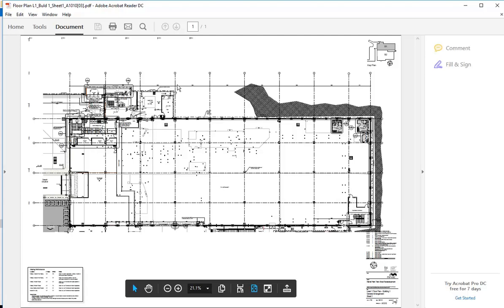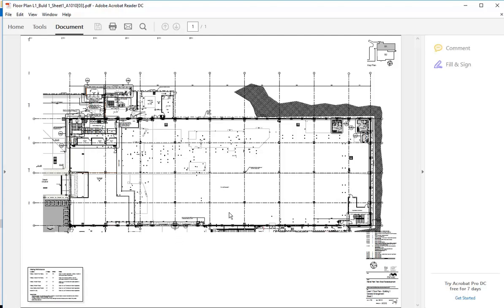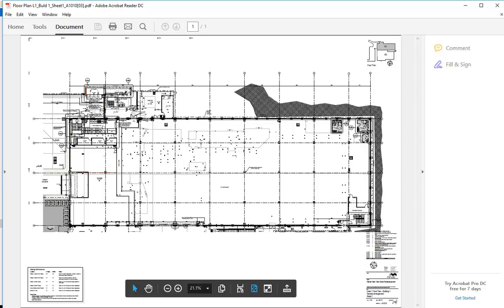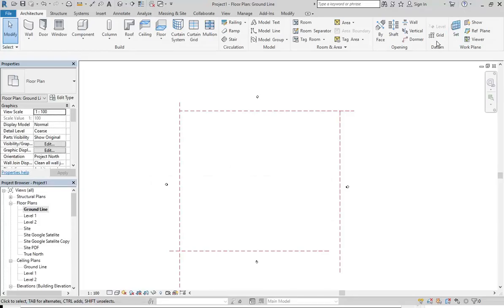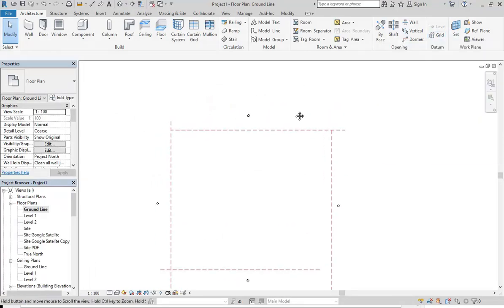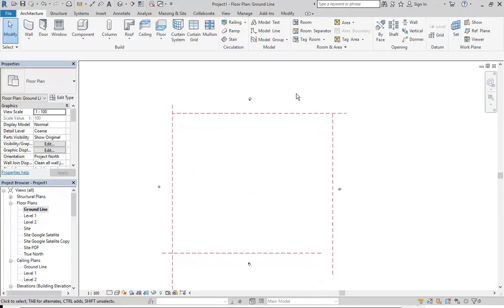I'll probably come back to you on this and show you how you can use grids, and then you can scale everything perfectly and have your own grids. If it's a building that uses grids, it's definitely something you should use. So make sure you know about the grid tool if you haven't used that one in Revit. That's all there is to it, but you can use the same process for any project, of course.